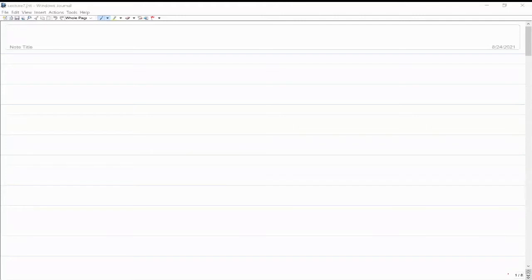Sir, in the total potential energy functional, in the integration form, there is d omega by dn transpose into Mn. Sir, what is Mn? Mn equals Mx, My. M is the moment per unit length. On which plane is the moment? The plane having outward normal along X, along N, outward normal along N.